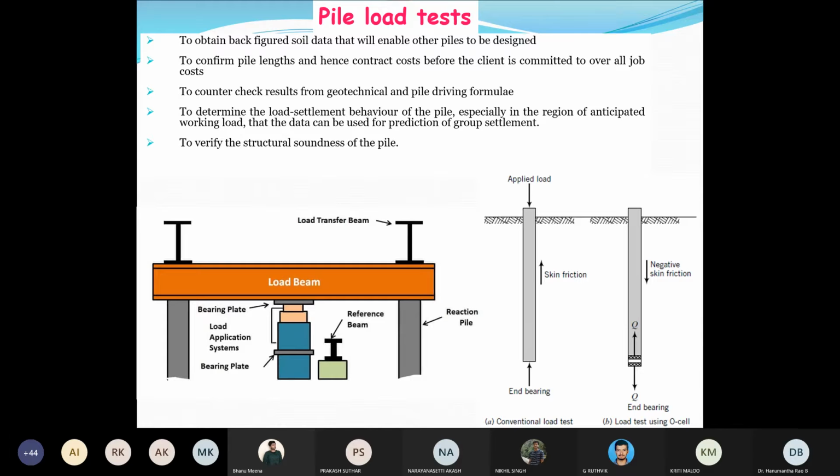They take one large funnel, where the mouth of the funnel is on the ground surface, but the tip of the funnel is at the required depth, say 30 meters or 40 meters. From the mouth, they feed the concrete, and through this narrow tube it goes to the tip of the funnel, and there it places the concrete.